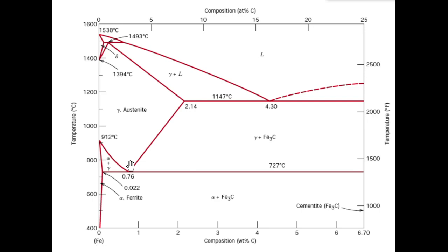And usually on these phase diagrams, when you have a three-phase invariant reaction, you have a composition marker around that area, and also an isothermal line, right? Isothermal line gives you the temperature for the reactions. So in this system, you can see that there are three reactions.